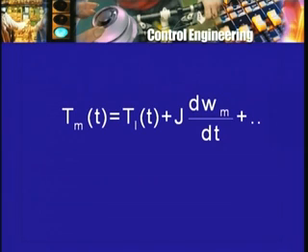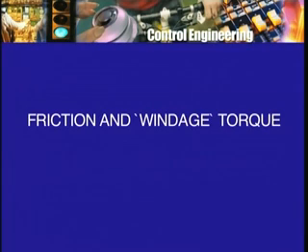the shaft is mounted in some bearing. There may be a cooling fan on the motor shaft. As the fan rotates, there is resistance of the air. So all of this we can think of as some kind of friction, and therefore an opposing force to the rotational motion of the shaft and the armature.